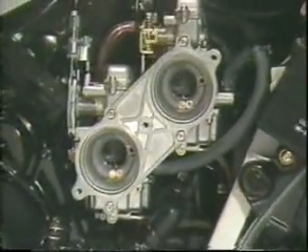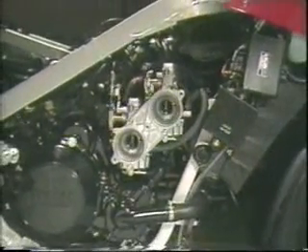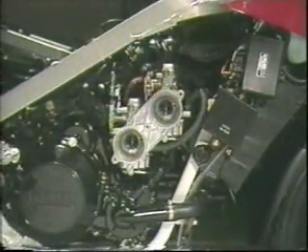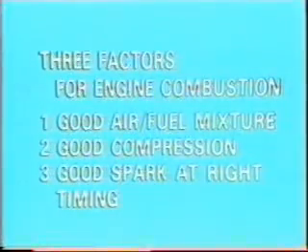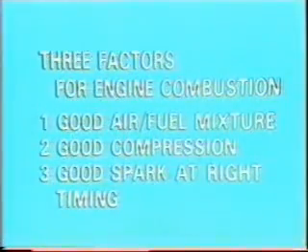We have now reviewed the different parts that control the fuel amounts at various throttle openings. Before carburetor troubleshooting, two things must be checked. Is the compression good, and are the sparks good? Only when the answer is yes to these two questions may you begin the carburetor troubleshooting. When the engine does not run smoothly, you must find the throttle opening range of the engine where the trouble starts.